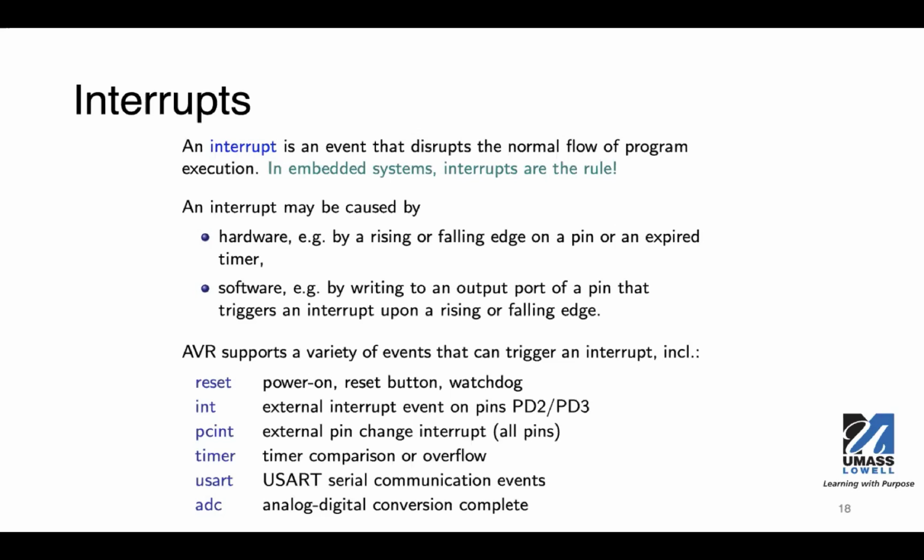And you have this PCInt. Those are also external pin change interrupts. But as we'll see later, these interrupts are not specific to a particular pin. Instead, it's all the pins for a particular port. So you have to have additional code to check which exact pin caused the interrupt.